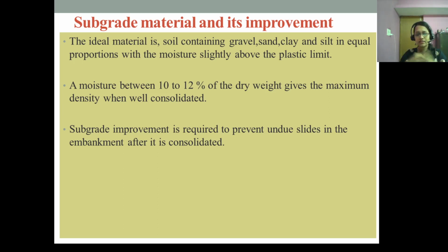Clays in particular, like black cotton soil, or even clay soils with particles having rounded edges, are very dangerous, right? Contact of these soils with moisture causes them to swell, resulting in the sloughing of the bank. In such cases the soil has to be improved.